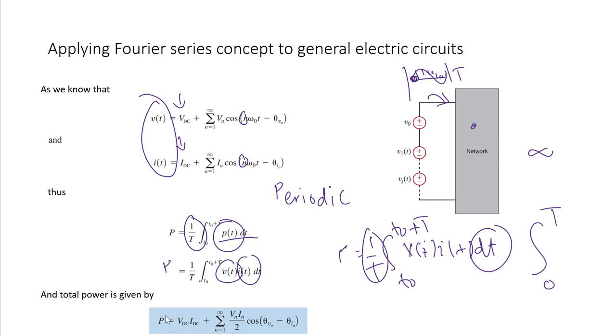So this is our power P. Now this power will have two components as usual, the DC component and all the AC components. The AC components are multiplied by this cos of theta. Why? Because we are interested in real power. So real power will have this cos of theta, and the imaginary power would be neglected, and we are using Vn In by 2 since it is the averaged power over an interval. So if the interval is calculated by this cos, we are left with this 2.